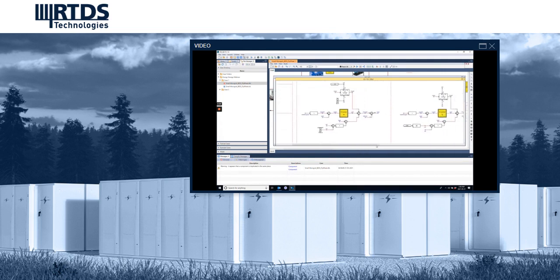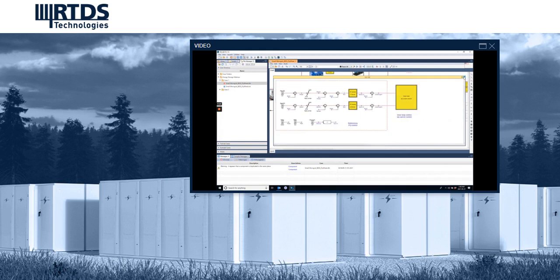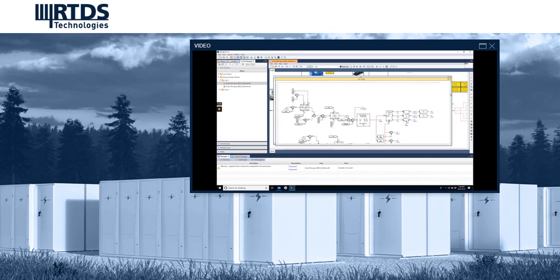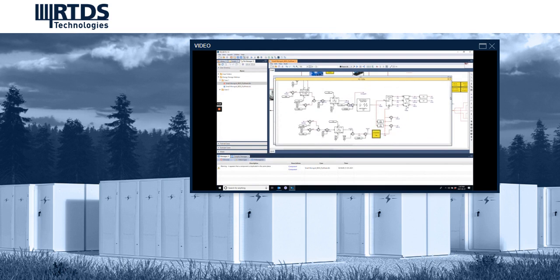A PI control is used to regulate the error for the D-axis current reference and the error for the Q-axis current reference in order to limit the battery AC side currents. When the microgrid is islanded, the battery switches over to a droop controlled mode in order to maintain the power balance in the microgrid.